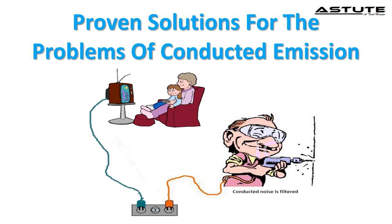Add a choke to the DC output ground lead. Add a common mode choke to the input circuit. Reduce transformer interwinding capacitance.